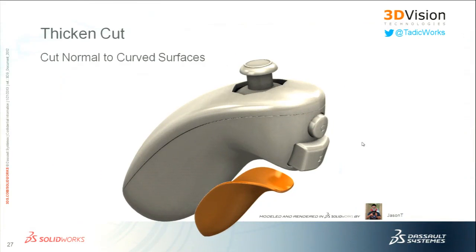Question? Yep. When you did the cut, did you put draft on that cut? No, it's actually cutting normal to the surface. So I could, as a separate feature, maybe add a chamfer feature to the edge of that. Unfortunately, that would be really cool if we could add draft to that thick and cut. I could see how that could be useful, but right now it's just cutting in one direction that is perpendicular to the existing surface. Okay?